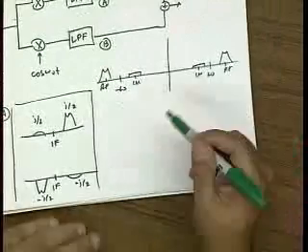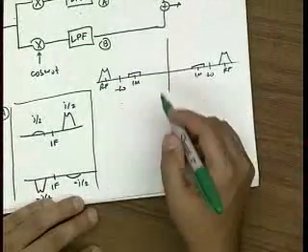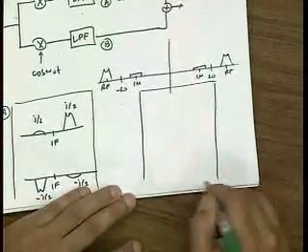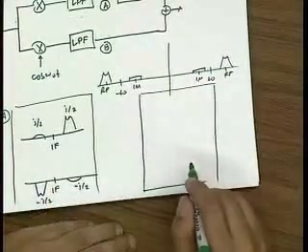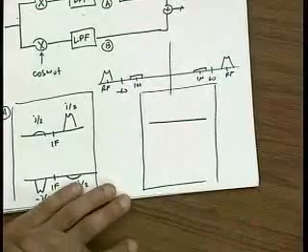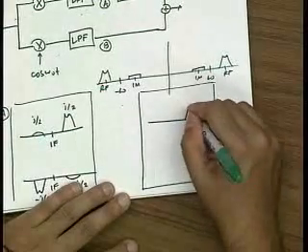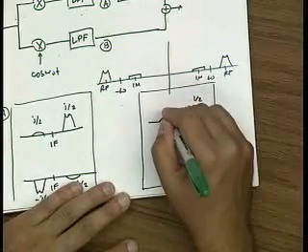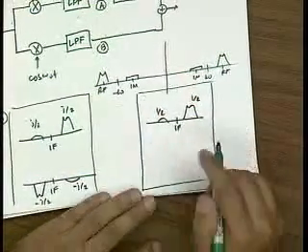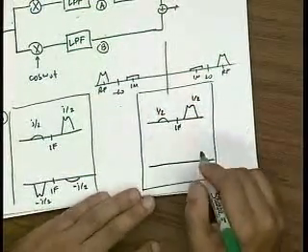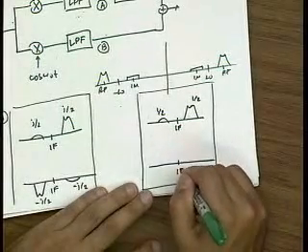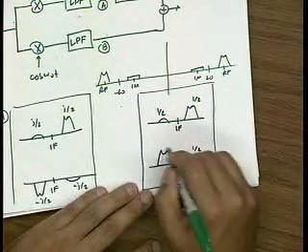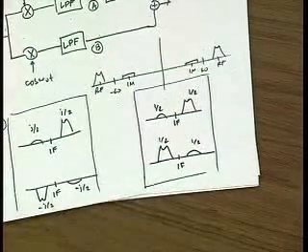How about at position B? Position B is also very similar. I just don't have those extra factors of negative in there because it's a cosine. So at position B, I also get a shift term with a gain of just 1/2 now. There's no j because it's cosine. And likewise, for the negative frequencies, I get the same thing flipped around. And again, there's no factor of j here.